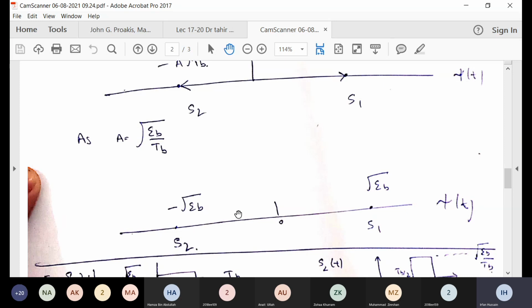And hence you represented your antipodal signal. And you can see in the antipodal signal, we have the same basis, and one signal is a 180 degree phase shift of the other, and the lengths of both of them are the same, which is the square root of EB, or its energy will be equal to EB.